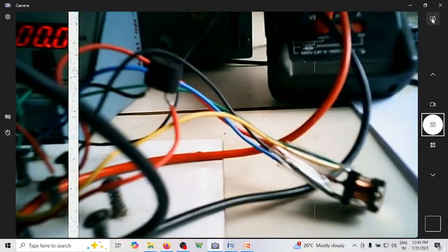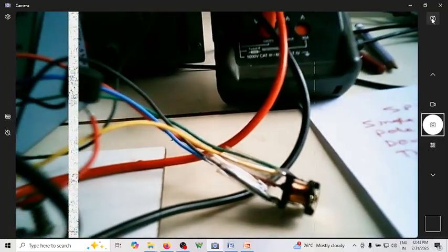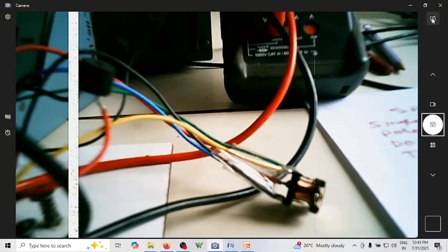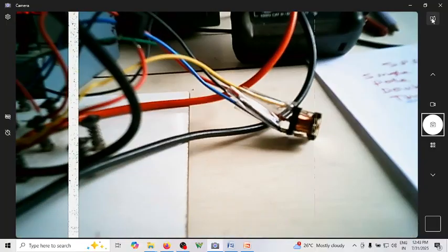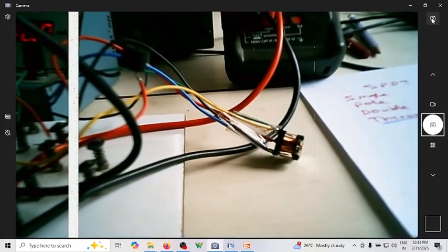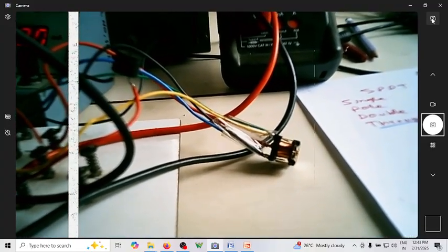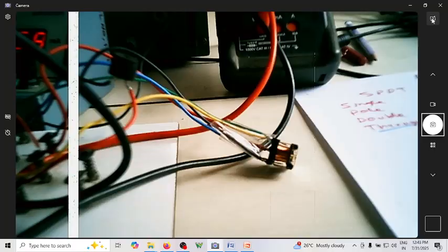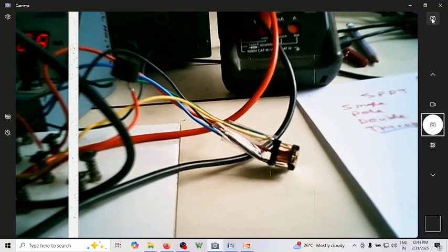When I press the button, that actually goes down. Can you see it's going down? Can you see when I release it, it went up? When it is going up, it means the common is now connected to the normally closed terminal. Whenever I push, it is pulled down. Can you make that out?